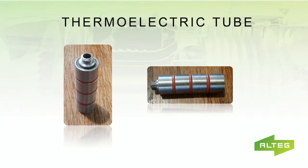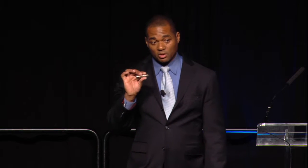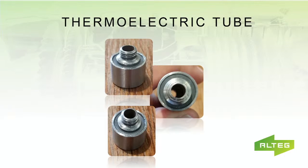So instead of something that was planar, where you had a hot side and a cold side, now you have a tube shape. So now your hot side is whatever runs through the interior of the tube, and your cold side is whatever is on the outside. Your heat sinks are now integrated into the module, and instead of being a fairly flimsy ceramic type material, this is now a very, very rugged, very well-built system that we can integrate into a heat exchanger. So each one of these modules can be threaded together to create a pipe.